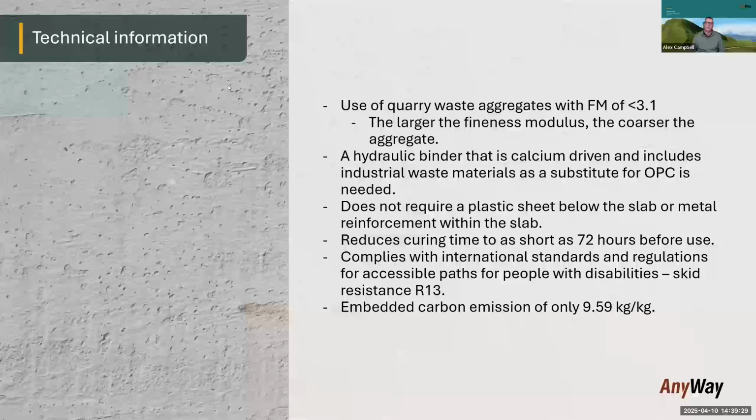We really try to eliminate the need of a plastic sheet at the interface between the aggregate and the slab, but also to do without metal reinforcement in the slab. That's not always traditional in sidewalks. It depends on the region, the climate, and the purpose. But to create a system that wouldn't use rebar was important for us. Fast curing times, or at least curing times that were not greater, were important so that we could have that solution trafficked or used much faster.